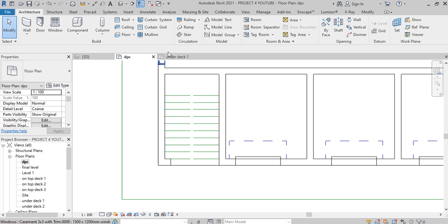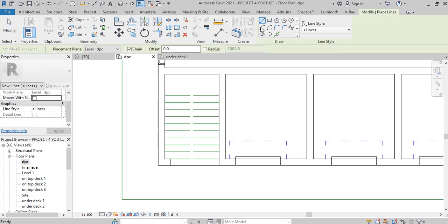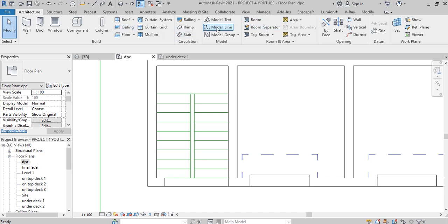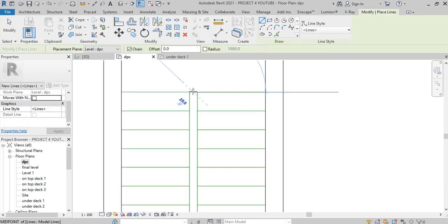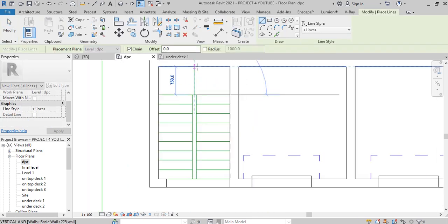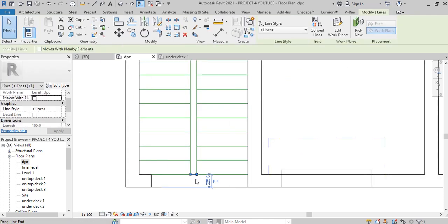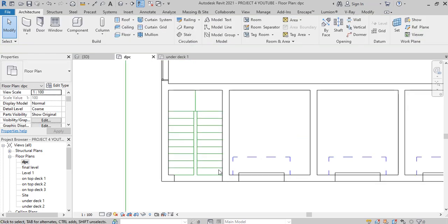In this case, we pick our model line once again, rectangle this time, and go to that point. I am also going to pick a line and make a line at the center point just to dissect both parts. So we have this and we have this. I'm going to remove this line. All this is just to guide us on what we are doing. So we are going to have 20 risers altogether to bring us to the headroom of 3000 millimeters.